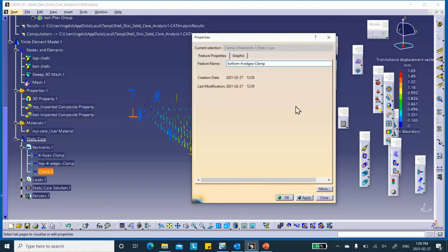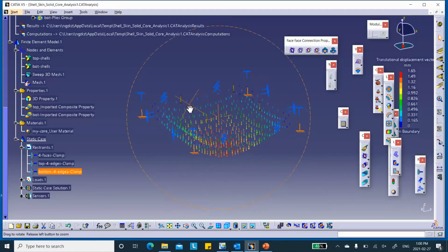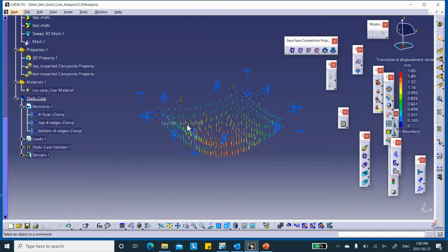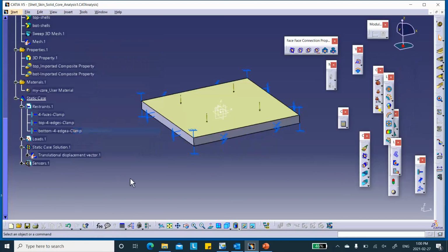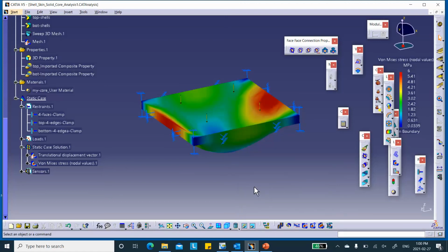Okay. Now, I want to show you a few things here. This is the same ballpark, so I'm not going to worry about that right now. Let's look at the stresses. When you look at the stresses, first of all, let me deactivate this, deactivate that. When you look at the stresses, here's one meso stress. You click on it, and you change the rendering to material shading. This is what you get.